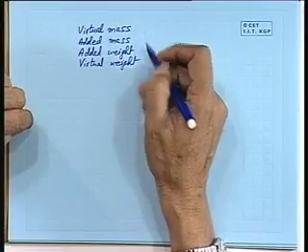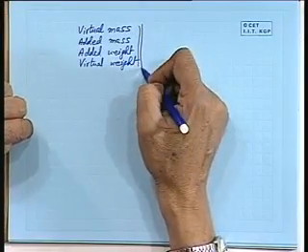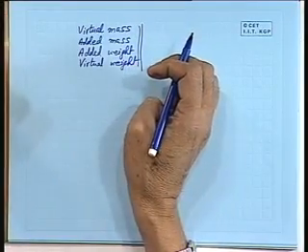When you go to the market, you say that you give me 4 kg of potatoes, there it is a force. But sometimes when you do the calculation, kg is in mass, sometimes it is with g, sometimes without g. So, these are interchangeably used, and one has to be very careful with the unit and the usage.